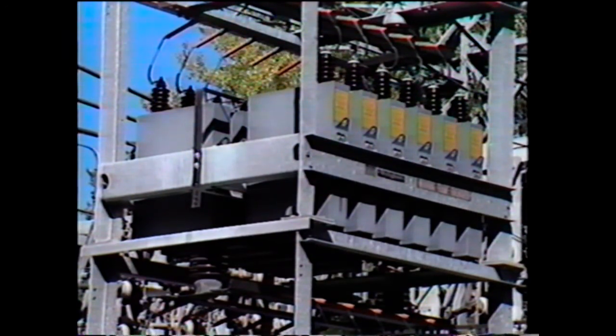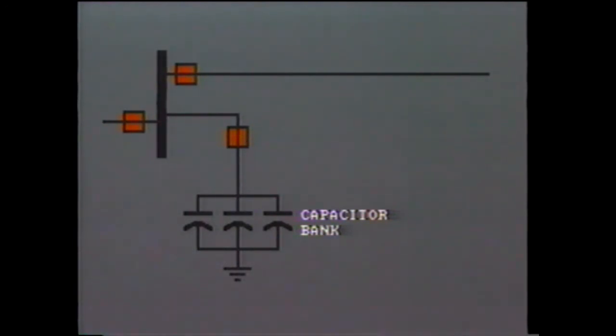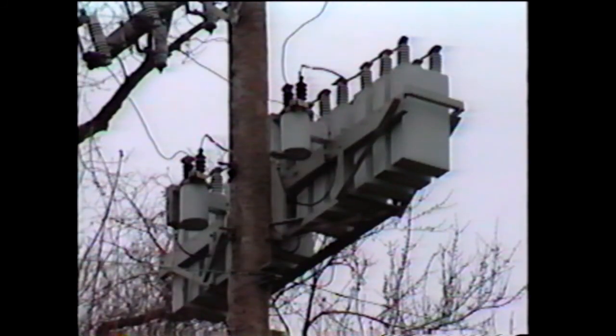While we're speaking of shunt reactors, we can also think of shunt capacitors. As you know, these capacitor banks are connected between line and ground or bus and ground in order to raise the voltage at that location by supplying VARs to the system. The capacitors actually compensate for the series inductance in the line and are commonly applied throughout the distribution system. The capacitors are susceptible to serious damage if a heavy fault current flows. The casing may rupture with consequent spillage of insulating fluid.